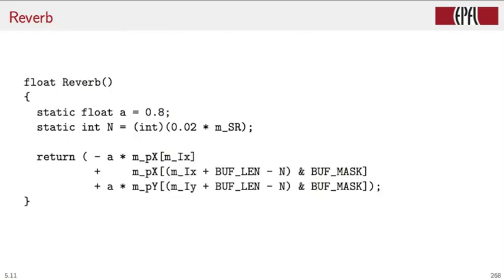The implementation of the all-pass filter is again extremely straightforward. We only have two parameters to choose, and then we just implement the constant coefficient difference equation in C. We can now try to apply the reverb to a little guitar snippet. We will play the original and then the processed signal.